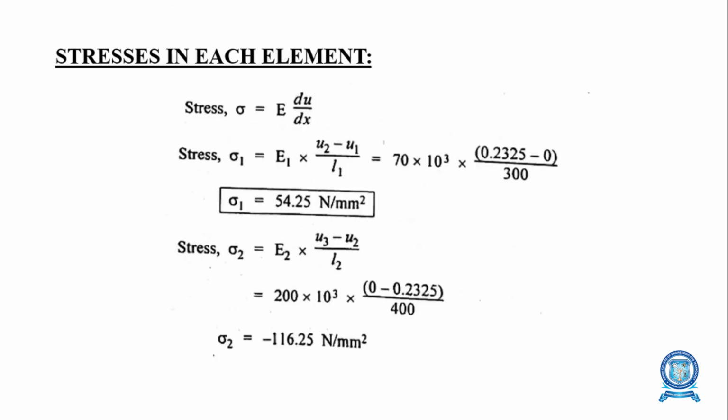Now, we are going to find out the stresses in each element. To find out the stress in the element, we are going to use the formula sigma is equal to Young's modulus into du by dx. Stress is equal to Young's modulus into du by dx.